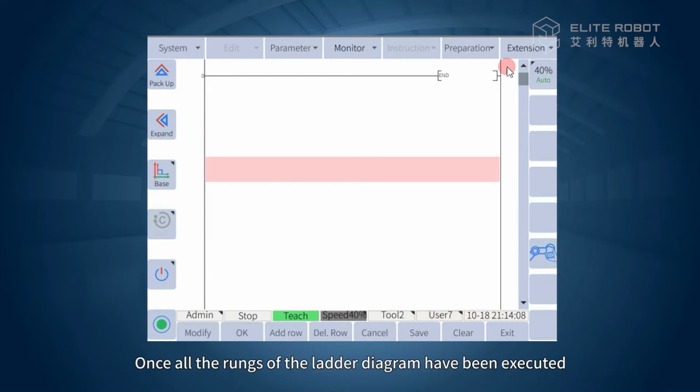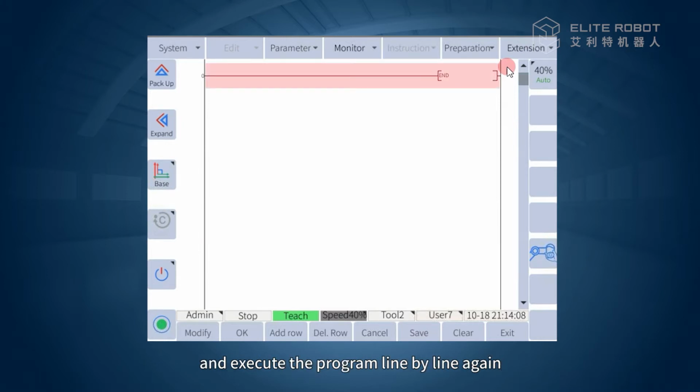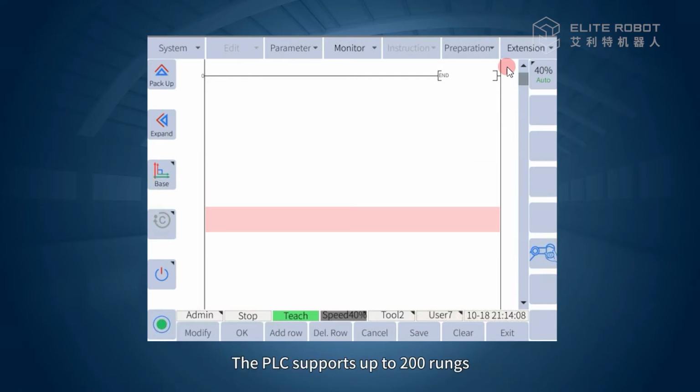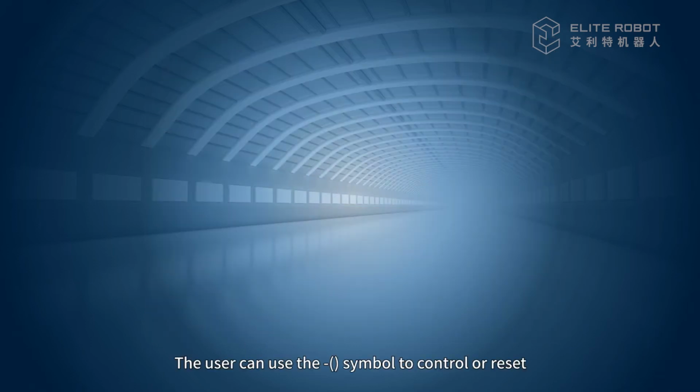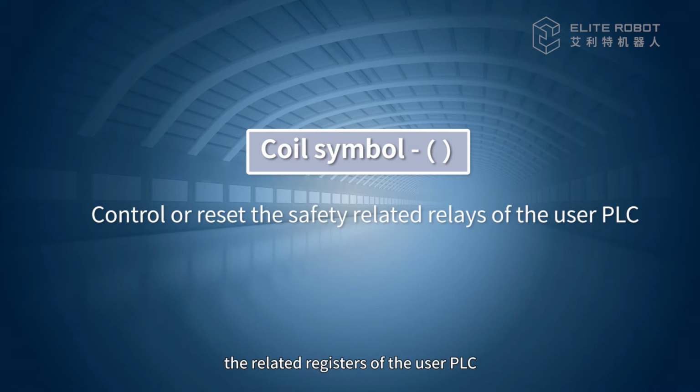Once all of the rungs of the ladder diagram have been executed, the PLC program will return to the top rung and execute the program line by line again. The PLC supports up to 200 rungs. The user can use the coil symbol to control or reset the related registers of the user PLC.